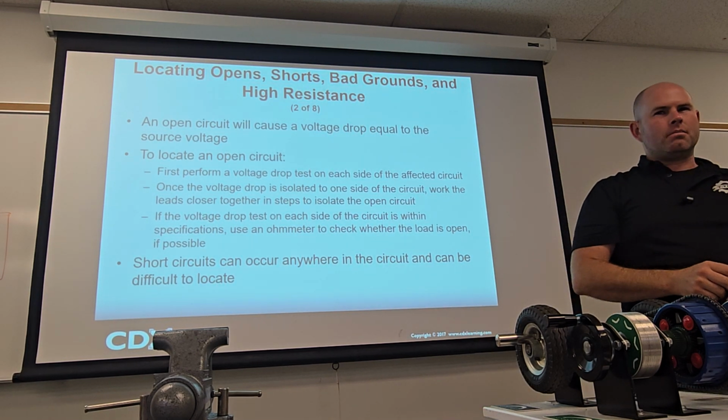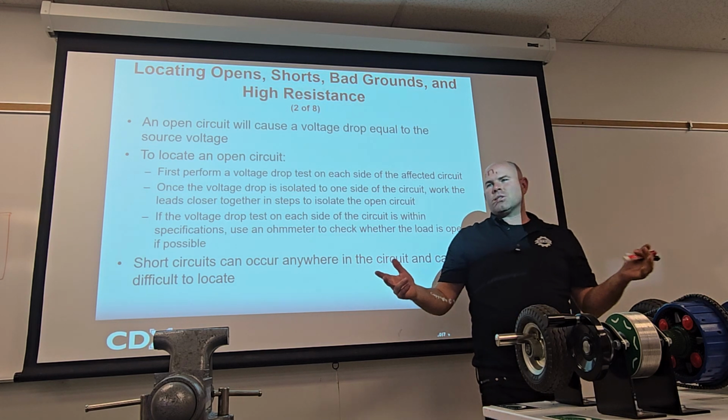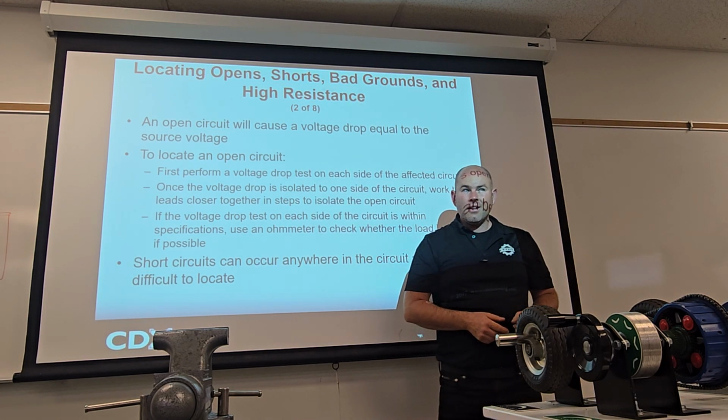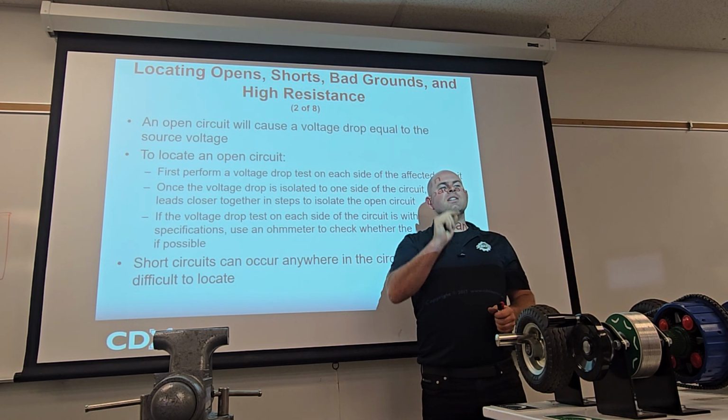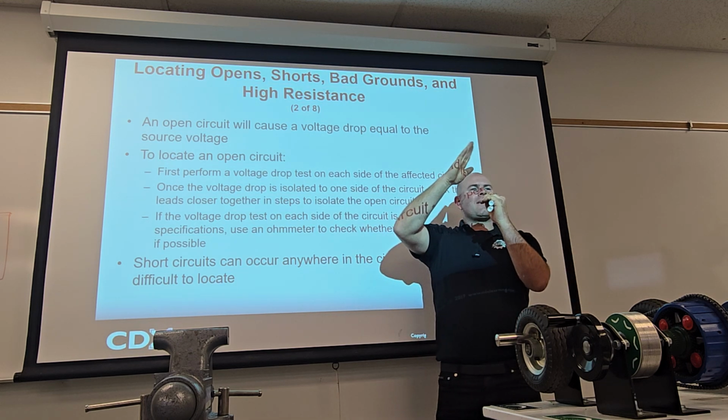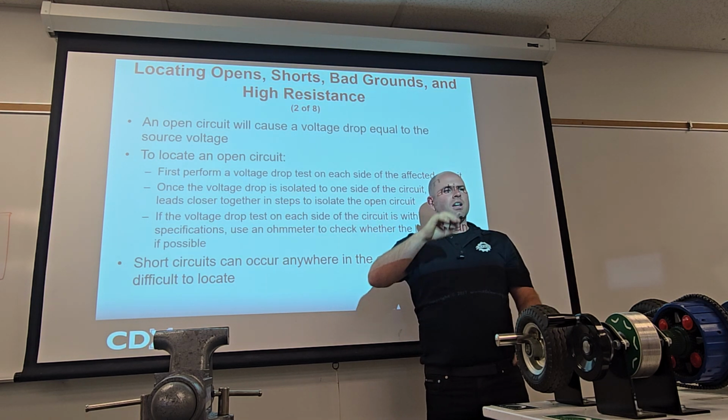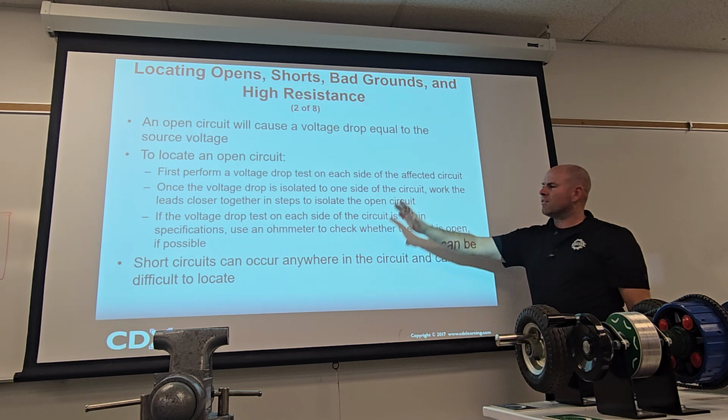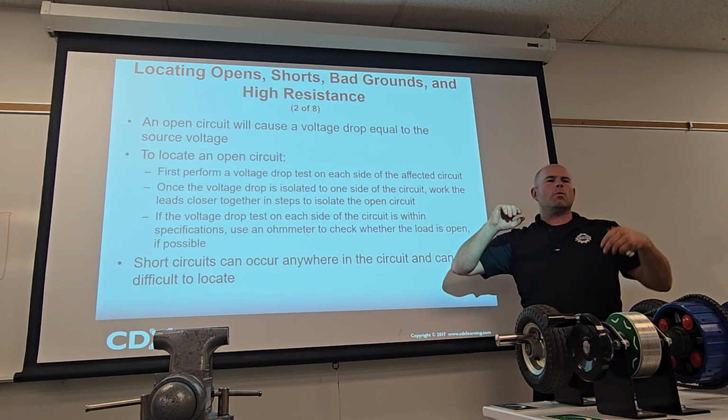Approximate. You guys have measured some bulb resistance. 4 ohms, 8 ohms, 12 ohms, I don't know. OL? No. What's OL tell you? The filament's open. Exactly. So you're really, right here, if you do these steps, you're proving...